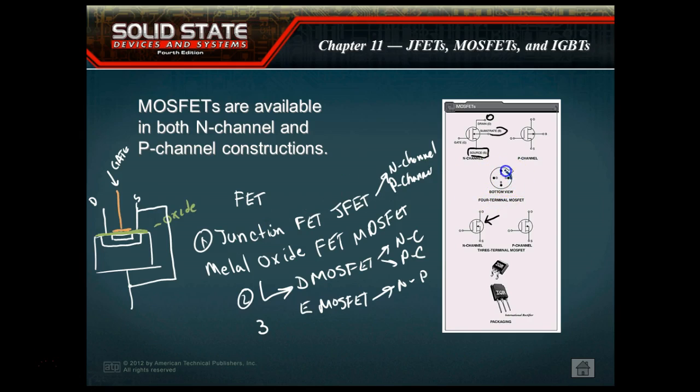They have a ring that goes around it, and it wraps around, and it'll have a little ring coming out here. So you can come up here and grab this with a pair of needle nose pliers and pull it off. But you need to wait to do that until you get it mounted and soldered into the circuit card, so that it can dissipate the electrostatic charge to the card. But you've got to remember to pull off that little spring before you throw power on the thing.